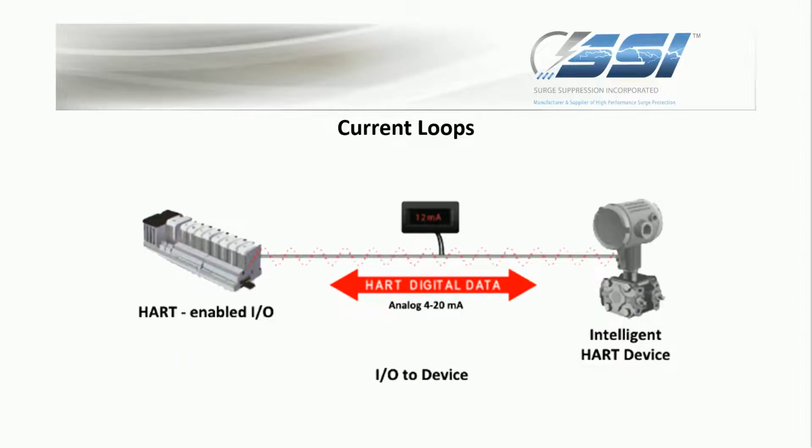The HART Digital Data System is a low-frequency signal that rides on the 4 to 20 milliamp loop along with the varying current. They are used for digital readouts, status, computer management, etc. Our standard current loop products will not interfere with the signal.